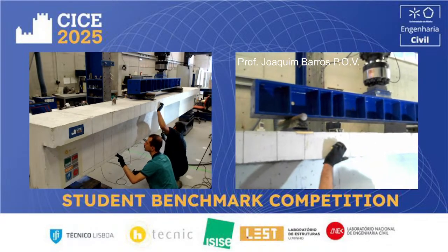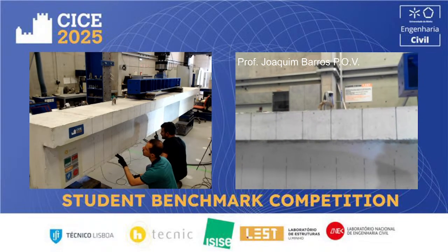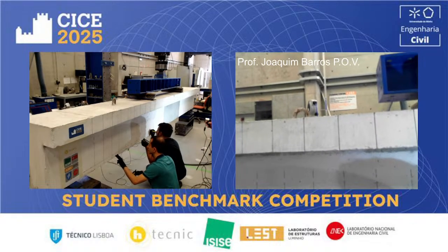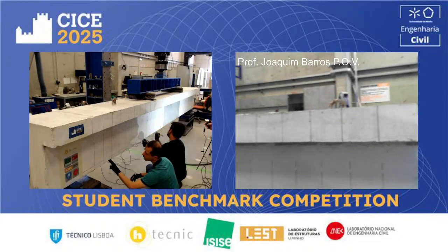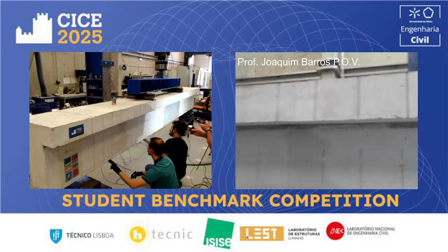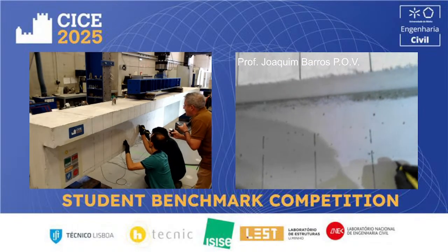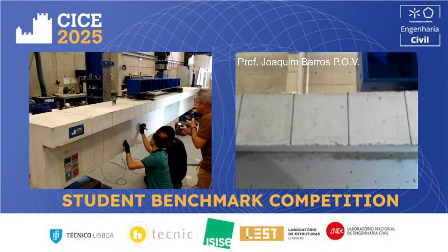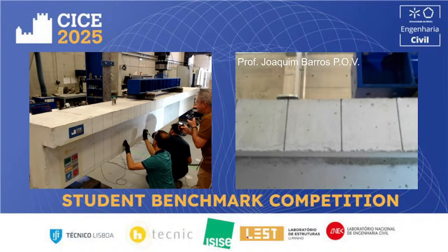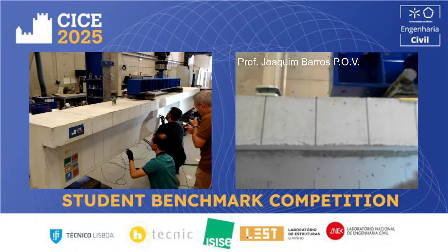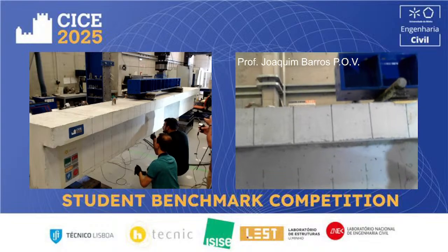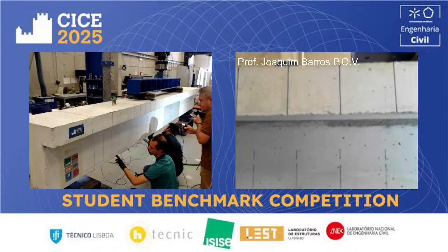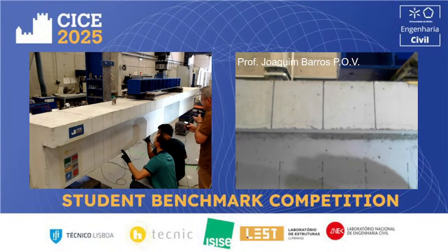115 kilonewtons. So it's amazing that up to now, 117, no cracks were detected in the shear span. Now first crack, 119. As you can see, this is a vertical crack, so consequently it is a flexural crack.